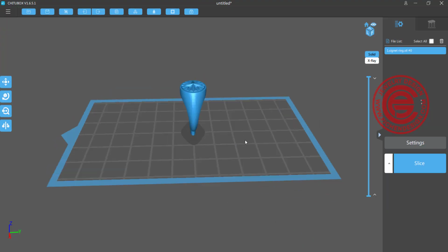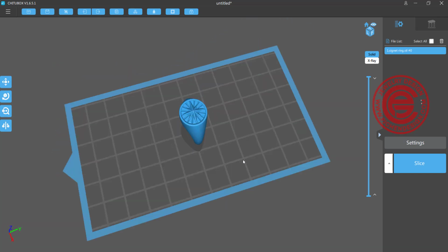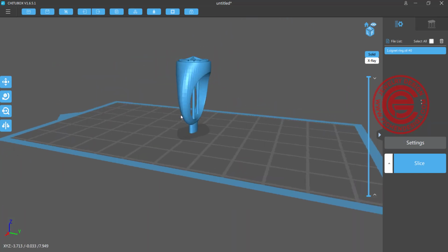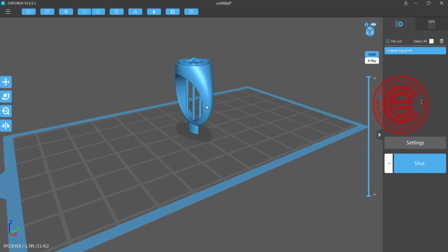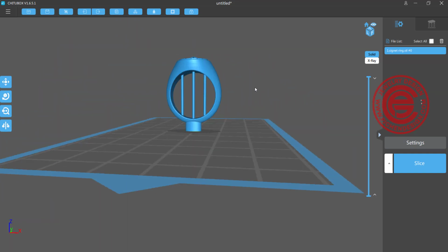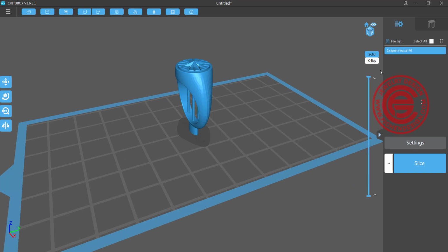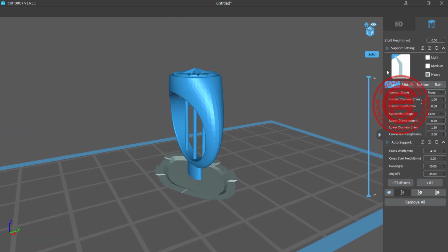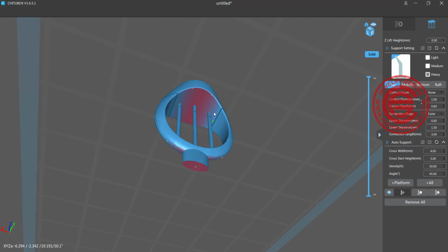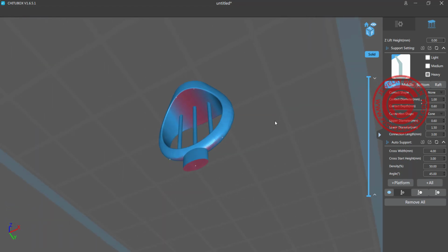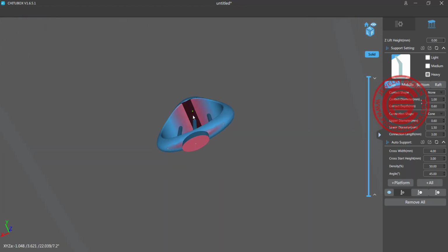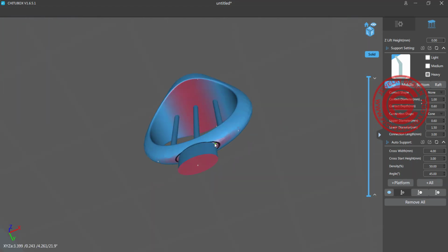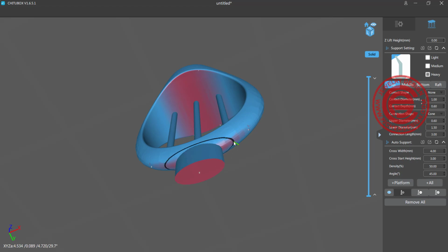So next I'm going to open the file and bring this into the G2 box. Okay, so I'm using the Phrozen printer, and this is the G2 box. It's free software. I don't need to make it even higher, so I just need to have a base over there. And you can take a look at this area. Anything marked red possibly won't have enough support, so you can manually add some pieces here, here, here, and here.